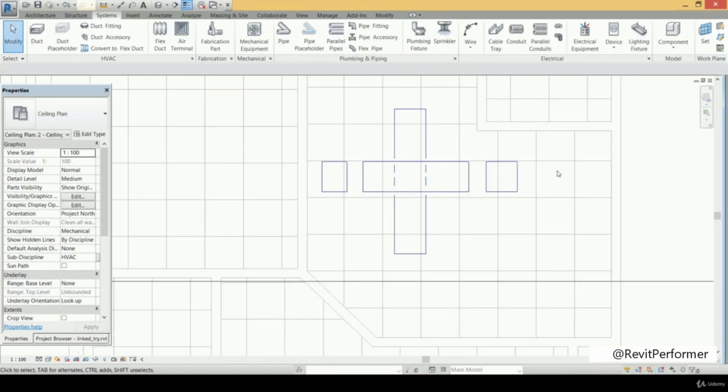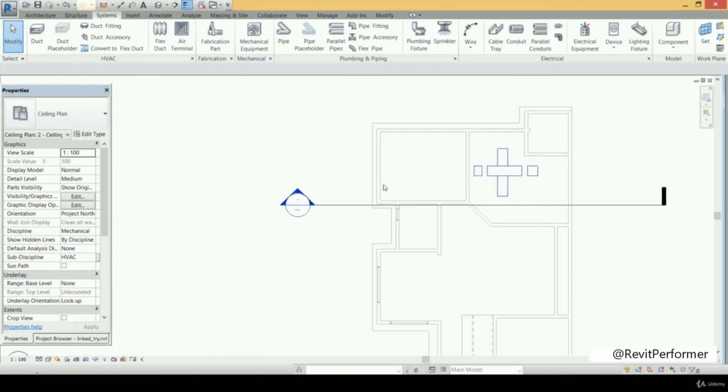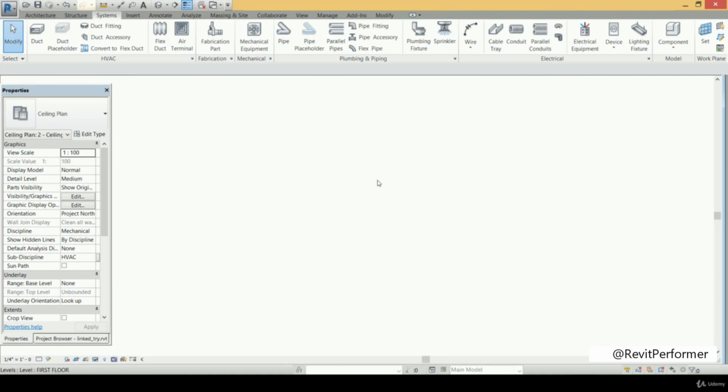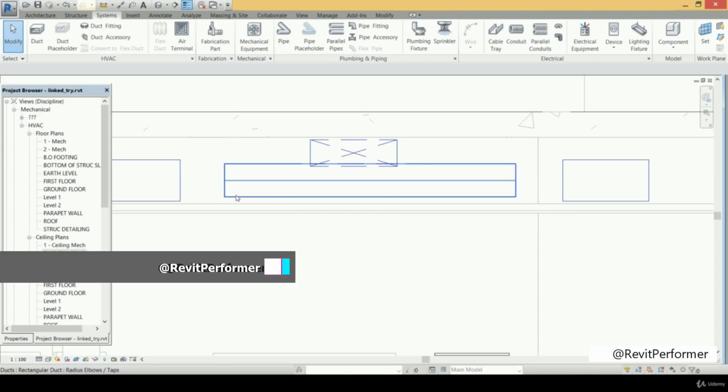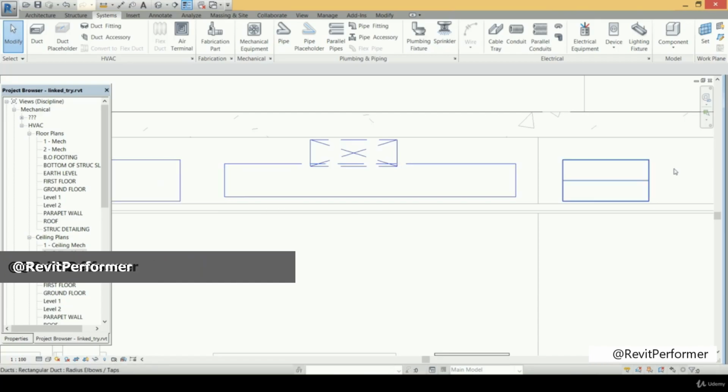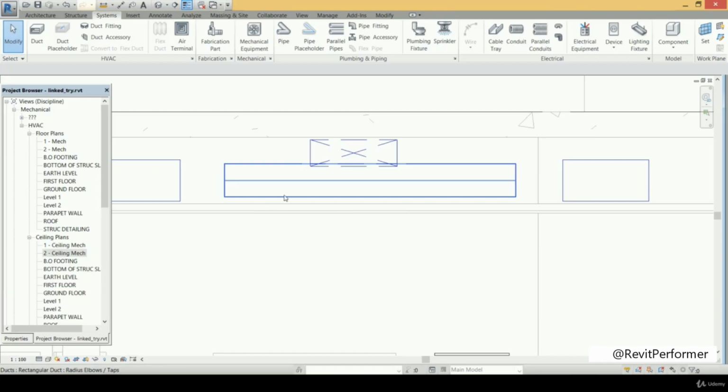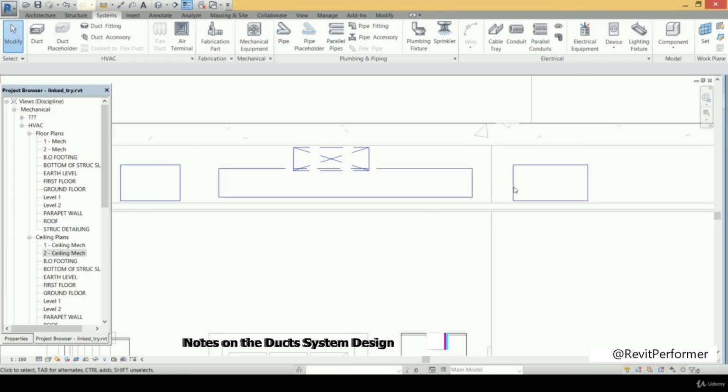And now let's see that construction from the elevation side of view, for example, to see what's going on well. Here we go to that section and double click on it. And as you see, those are the two parts that we have with the original dimensions, and this is the reduced duct, so we need to connect between that one and those two ones. But at first we need to make the height of that duct on its offset to be the same as that one and that one, and for that we will align its face or its down surface with the down surface of that duct and the down surface of that duct.